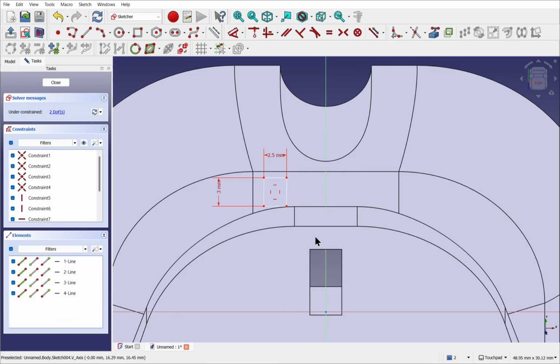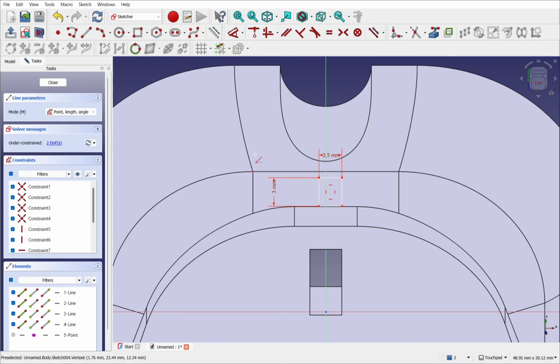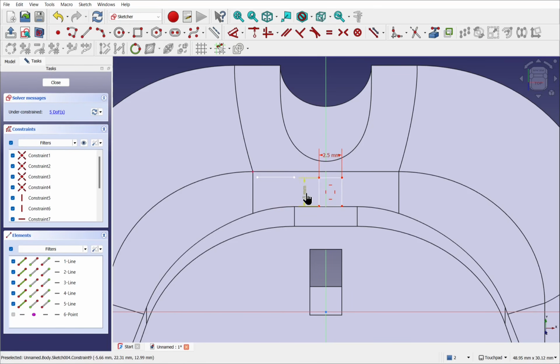This is where construction geometry comes to your rescue. Let's look at the anchor point first. Import the geometry and set an anchor point at this point. So if I place a dimension between this point and this point, it keeps that a certain distance away. But that's not going to repeat going this way. So instead, let's add another line and place a line in here, like so. Right click to cancel. Let's move this dimension over this way.